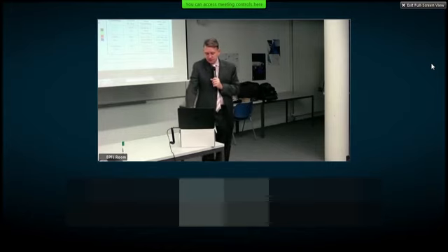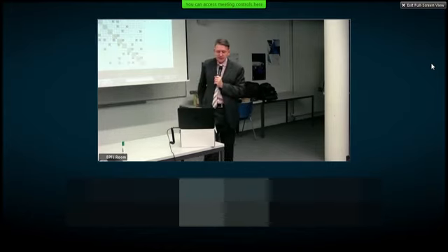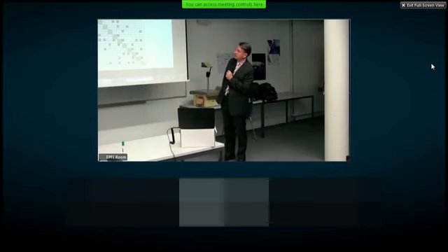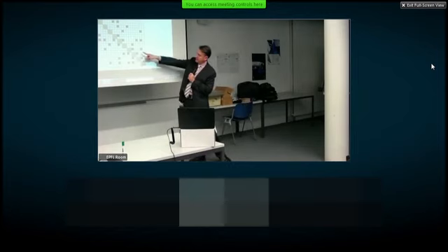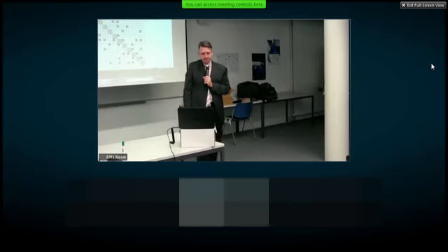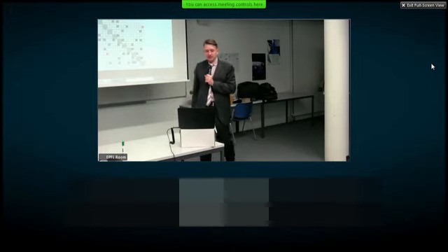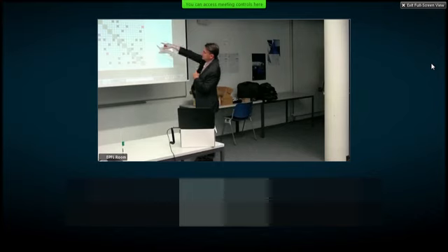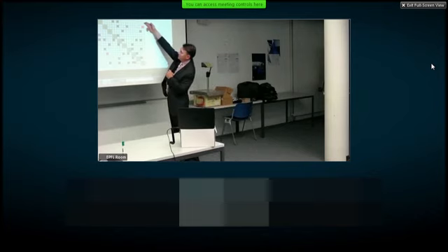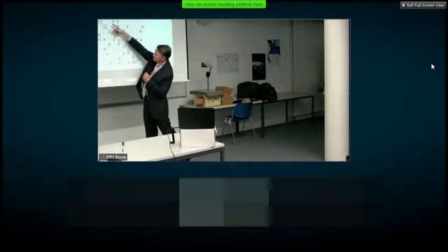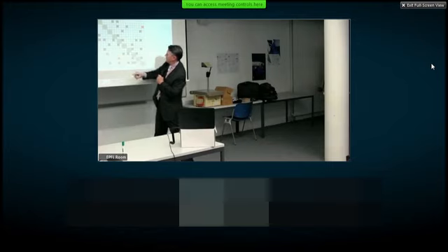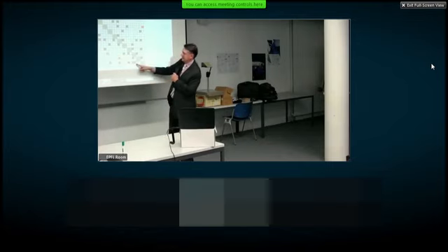If we apply that idea to the refrigerator, here's our 10 by 10 physical connections. We have a design structure matrix with only the black marks, so it's symmetric, and this reflects the liaison diagram. Then we can add on top of that the mass flows, which are in red. The way you read this is we have a mass flow from the compressor to the condenser, and then from the condenser to the evaporator, and then from the evaporator back to the compressor.